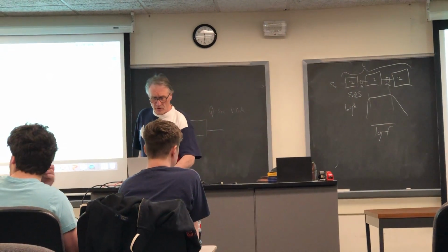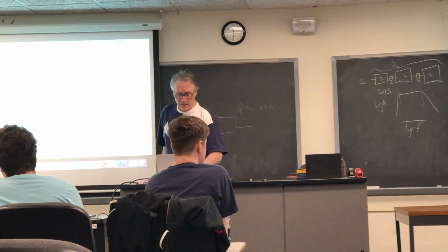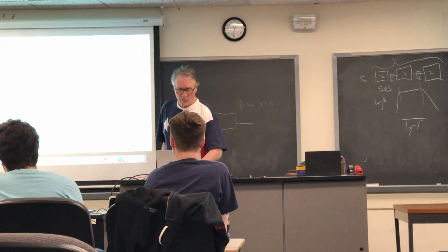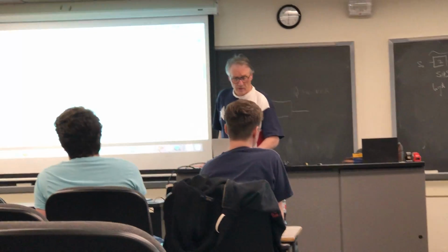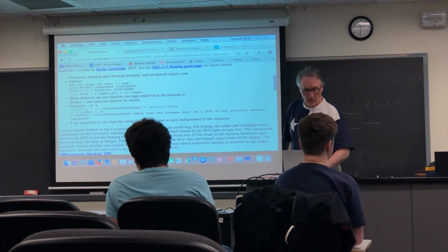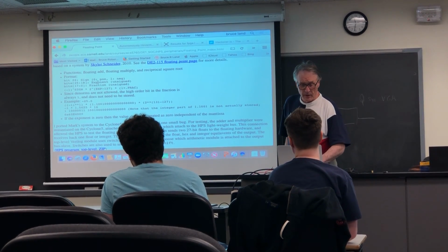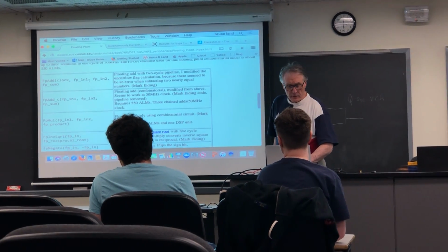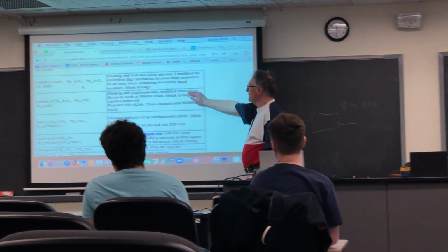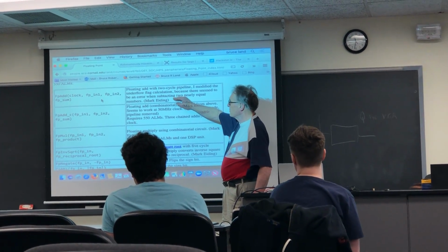So this version of the floating point that I'm talking about right now has an 18-bit mantissa, or more formally a significand, an 8-bit exponent and 1 bit of sign. It supports a floating point add in 2 clock cycles for pipeline for faster execution.